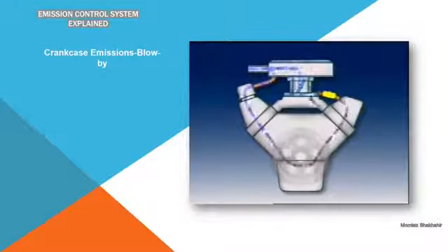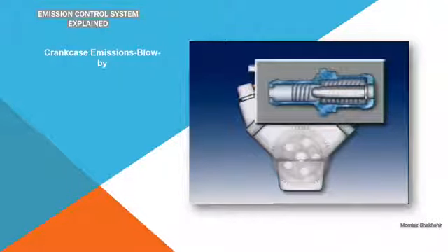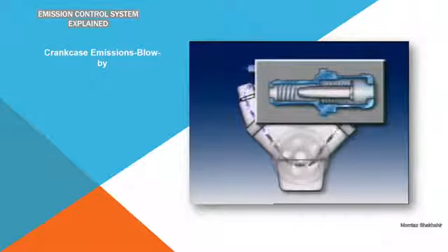A valve called the PCV valve regulates gas flow between the crankcase and the inlet manifold. It is controlled by the pressure in the manifold. With the engine off, the valve is closed and air cannot enter the inlet manifold. This allows the engine to start. At idle, low pressure in the manifold draws the valve to the other end of the body. This lets a small, measured amount of vapor pass the valve. At wider throttle openings, the valve plunger position allows maximum flow through the body, which gives maximum crankcase ventilation.